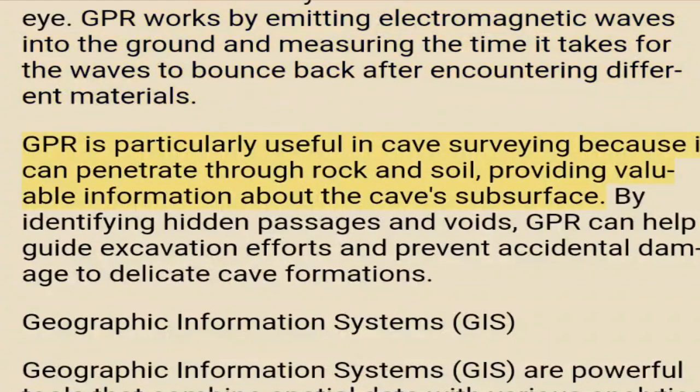GPR is particularly useful in cave surveying because it can penetrate through rock and soil, providing valuable information about the cave's subsurface. By identifying hidden passages and voids, GPR can help guide excavation efforts and prevent accidental damage to delicate cave formations.